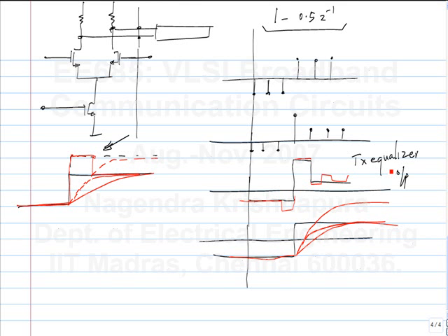If we have digital data, whether you have a sample and hold or a D flip-flop, it's the same thing, because a D flip-flop is a sample and hold that works only for digital signals. If you apply a different amplitude, it will still hold the same amplitude. That's the only problem, so you can't use it for analog values. But for a digital signal, a sample and hold and a flip-flop are practically the same. Now, this is only on the transmitter side, and I don't want to use this flip-flop or FIR based approach. What else can I use?